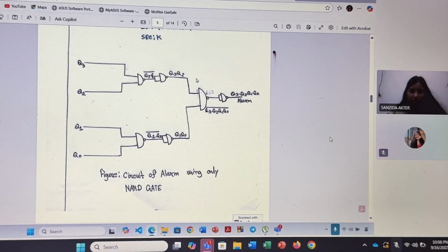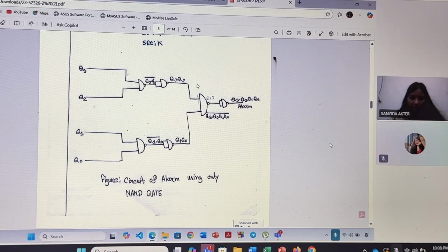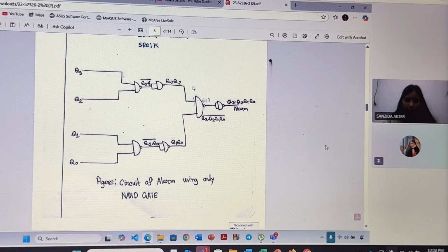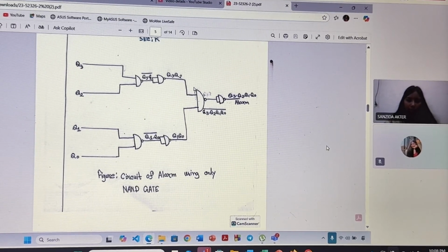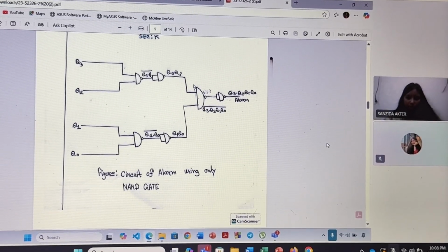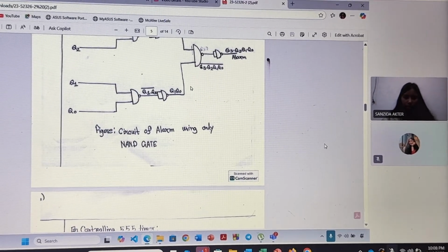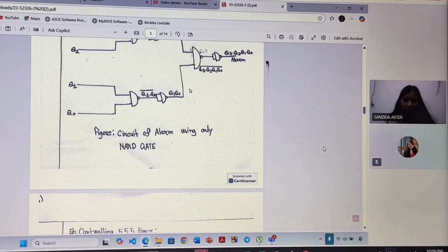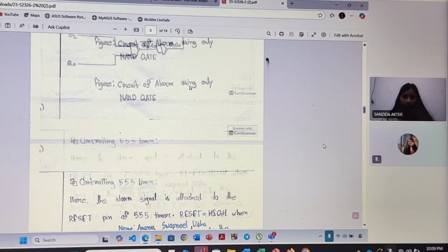To implement this using only NAND gates, I designed a standard NAND configuration that performs the equivalent AND logic. Whenever Q1, Q2, Q0 and Q3 are high at the same time, the NAND network outputs a signal that immediately drives the 555 timer warning of excess crowding.